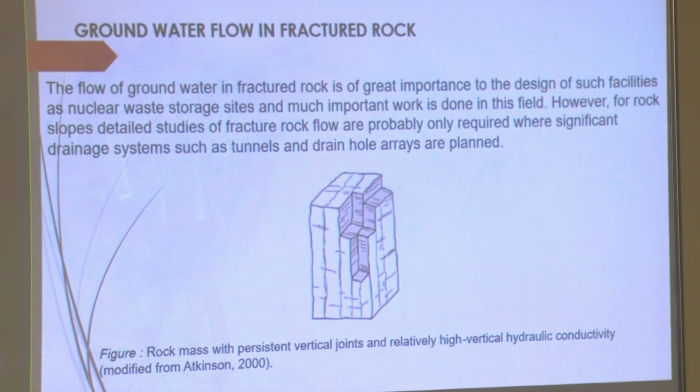This is basically to give you an introduction, because in rock slope, this discontinuity plane actually plays a very important role for the flow of fluids. Because rock porosity is very less, rock permeability is similarly very less. So generally fluid is susceptible to flow along the discontinuity. Along the intact rock they do not flow. That is why we need to characterize the joint distribution.